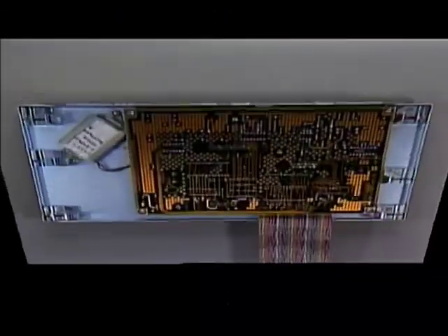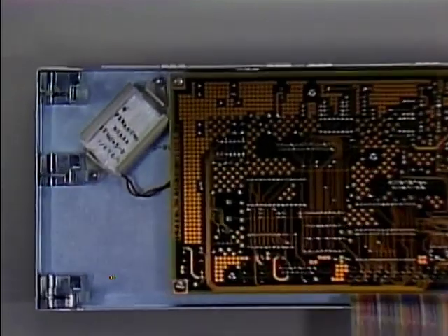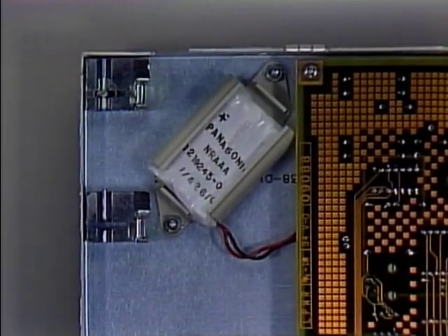The reverse side of the cover assembly contains a logic module that acts as an interface between the I/O cover cable and the I/O connectors. It contains the thin wire transceiver logic and the drivers and receivers for the serial lines. This battery is used by the workstation I/O module during power failures to maintain the time of year clock and battery backup RAM. If the I/O cover cable is disconnected, the battery is also disconnected, and the information in the TOY clock and the BBU RAM will be lost.